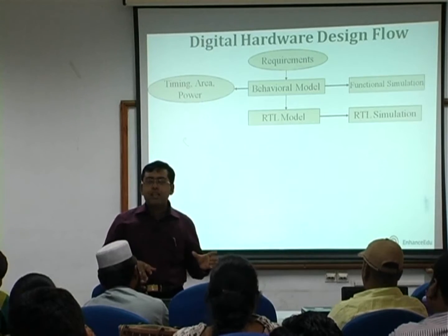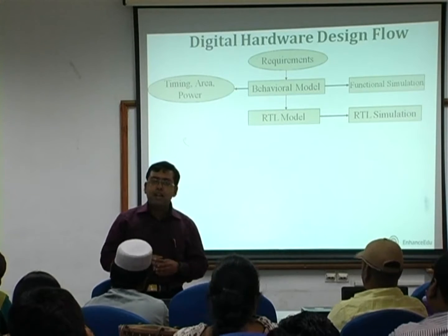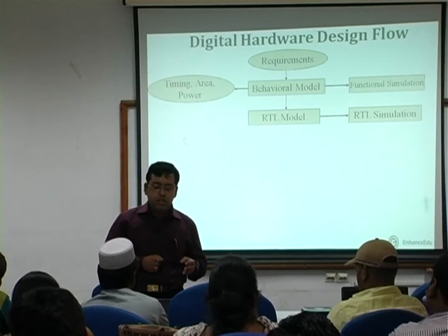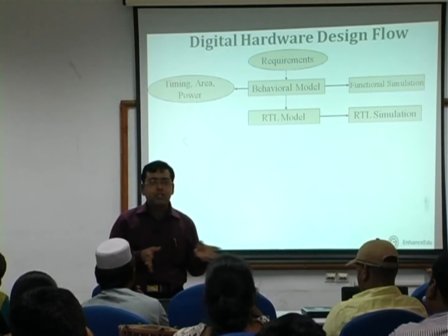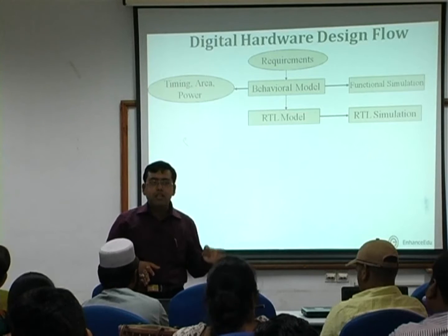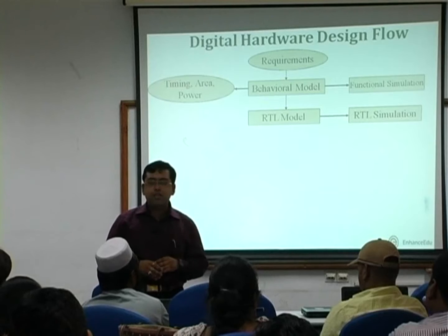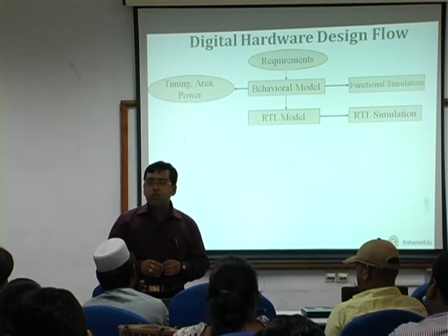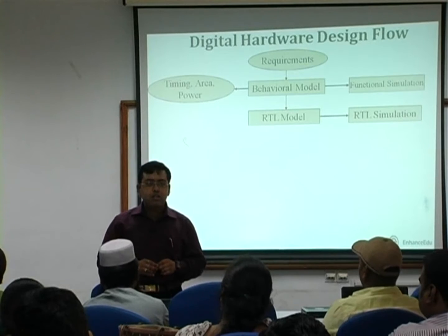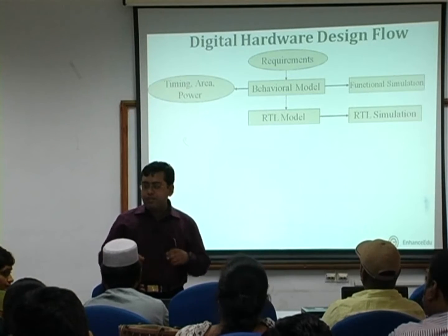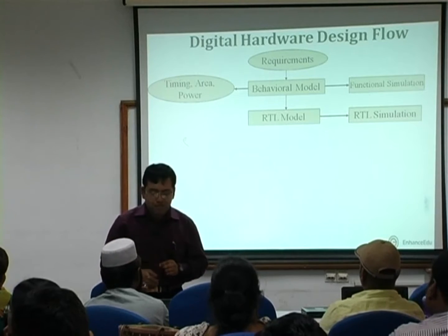We don't take care of all the signal integrity issues, timing, and other issues when we talk of the RTL model, although we do the timing simulation, but in the design itself we don't directly take into consideration all the low level effects. I am in fact going to talk in detail about simulation in the course of my lecture.